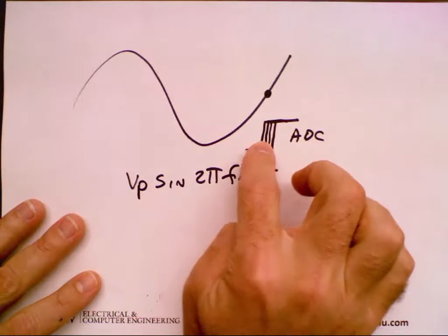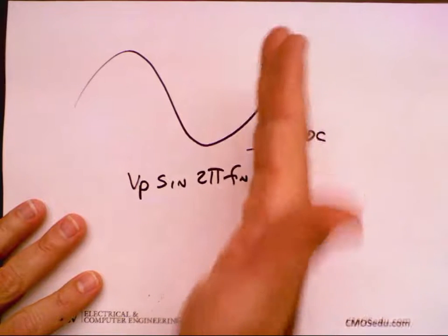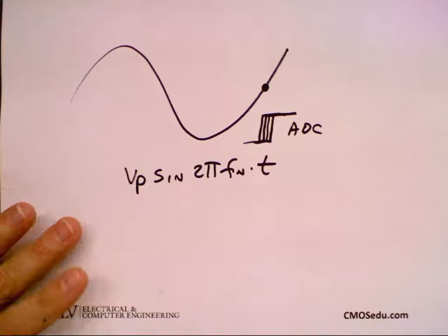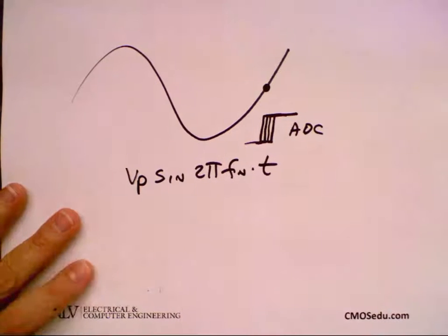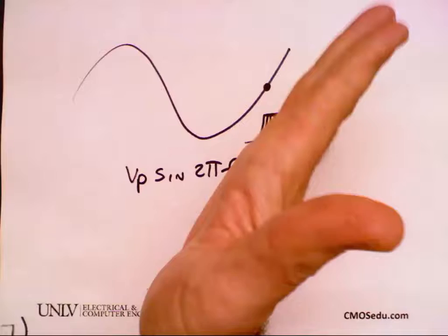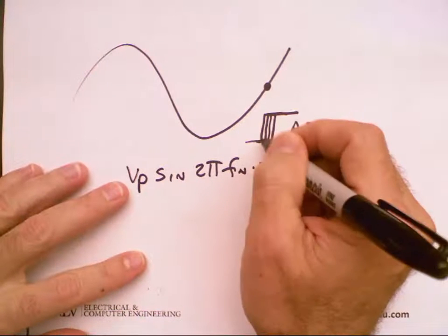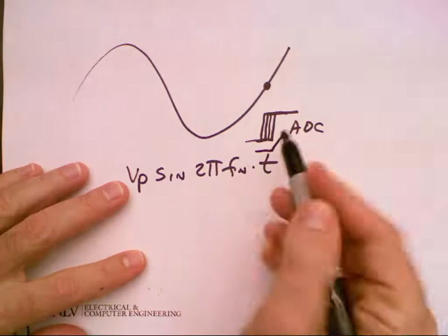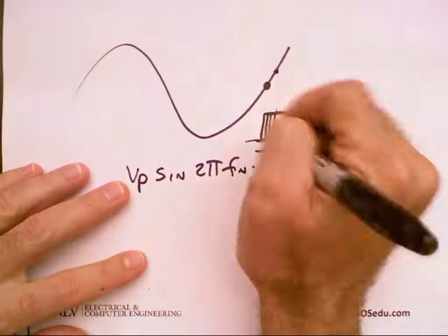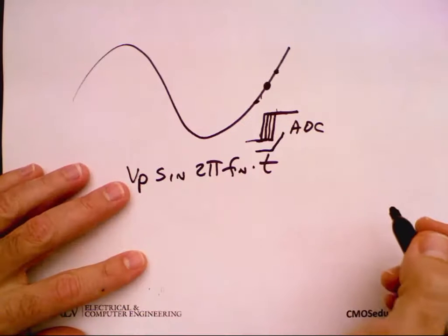You're not hitting it because the clock is moving back and forth. You're not hitting it in the right exact spot. Any questions? Now you might say, well, it's really tiny. Before I go on, do you think that clock finite rise time would also be an issue here? If your clock has a rise time that looks like this, instead of sampling, if it's doing this, can't you see it's going to give you exactly the same problem? If you're clocking here, you sample there. If you're clocking there, you sample there. Does everybody see that?